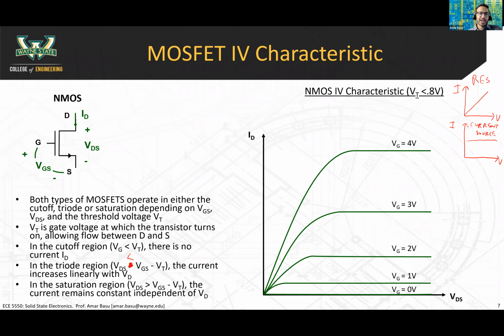So that's more how you can think about the gate voltage: it's more akin to where that needle position is. As you apply a larger gate voltage, you can imagine that this little channel region is opening up wider to allow more current flow between the drain and the source. So that's why your curves look like this.